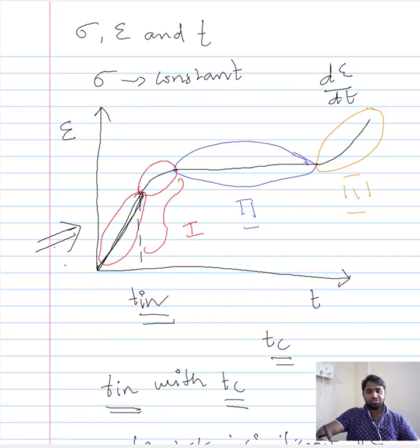That condition is the time taken for the instantaneous creep should be relatable to that of the overall time taken for the overall creep behavior or the overall creep testing. Only then will you be able to include this instantaneous creep region here, and only then will your stage 1 comprise of the instantaneous creep region and the transient creep region.